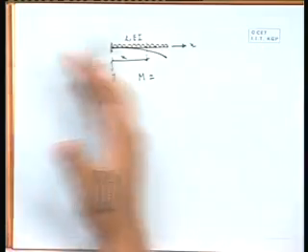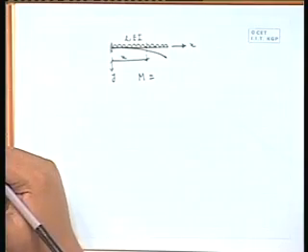So, our first job is to find the expression for the bending moment. Now, at any distance x, there is one cross section; what will be the expression of bending moment? We can calculate from the right end, because that is a free end, it is easier to calculate.